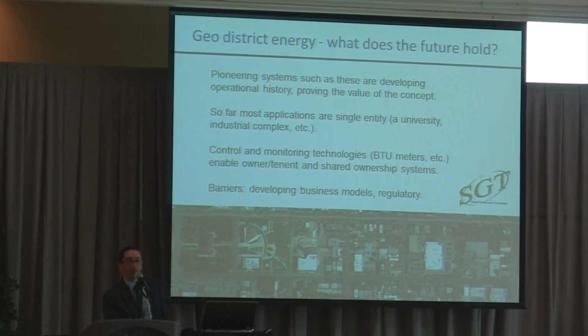The other case where you may have some issues, and this is mostly on the residential side rather than the commercial side, is that a lot of residential systems can use electric resistance heat for backup or emergency heat. And just like any mechanical system, if it's not installed and controlled properly, I have seen a case or two where the electric heat was wired such that it overrode the heat pump. So at that point, it's basically a toaster. But yeah, is it possible? Yes. Is it normal that that would be an issue? No.